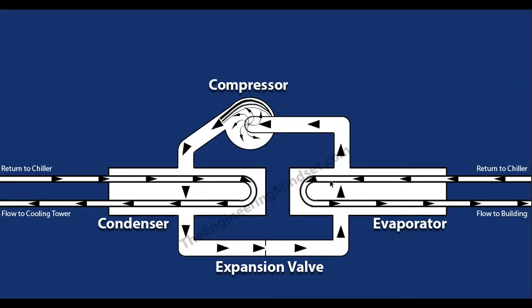You might be wondering about what's happening inside here. So the evaporator or the chilled water circuit is the water, if you remember, it's being sent up to the AHUs to collect the unwanted heat from the building, and that's returning at about 12 degrees, and it's coming back into the chiller, passes through the loop, and by the time it leaves again it needs to be around 6 degrees. Obviously the temperatures can vary a bit, it depends on the setup and design of your chiller, but this is for explanation purposes. So the water that's coming in is held within these tubes, and that keeps the water